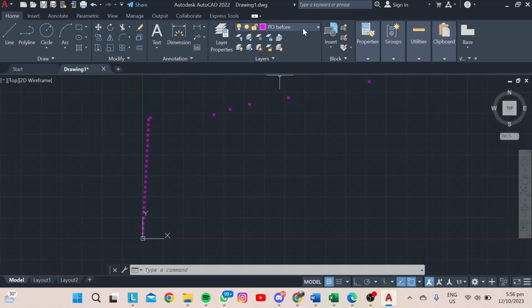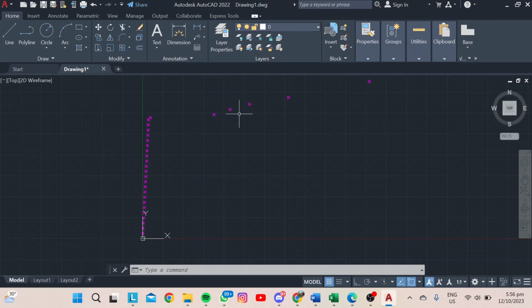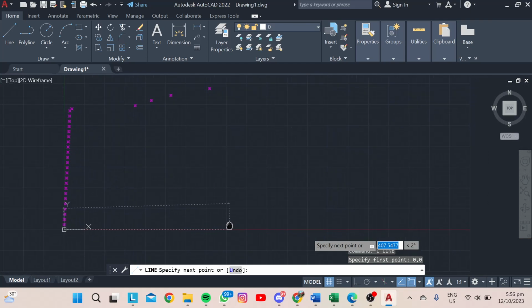And then you have to draw the axis lines, be it the axis Y and X. But before that, you have to change the layer into layer 0, and then type L on the command section, this section which has the color white, and click space, and then type 0,0, click space, then bring the line to the right side.